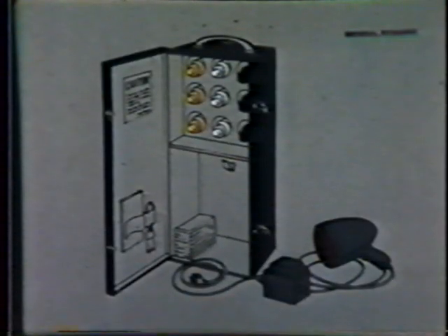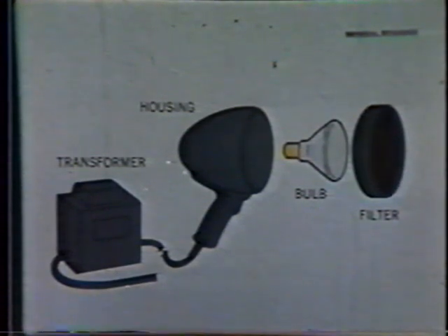The fluorescent kit is similar, except a fluorescent penetrant is provided, and it includes a black light. The light consists of a current regulating transformer, lamp housing, mercury vapor arc bulb, and a deep red-purple filter. What is black light? It is light radiation in the near ultraviolet range of wavelengths between 3,200 and 4,000 angstroms. Though it is invisible, black light causes many materials to visibly fluoresce or glow. Best sensitivity to fluorescence is obtained in a darkened area.